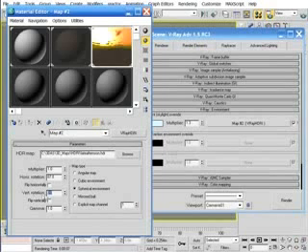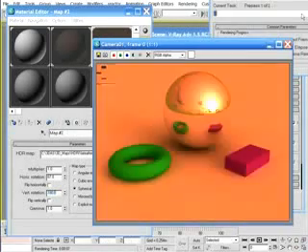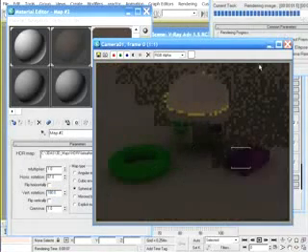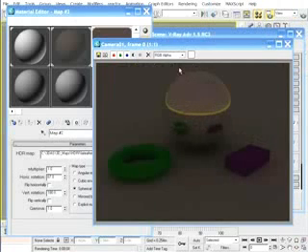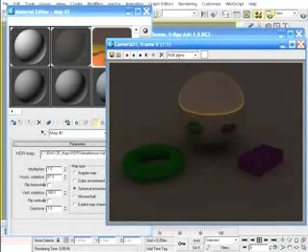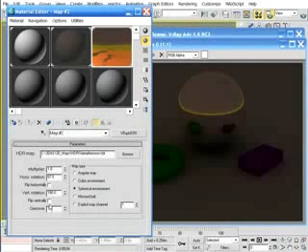And here's the same scene with 180 degrees of vertical rotation. Notice in the sample slot that the HDRI is now upside down. Now when rendered, the majority of the illumination seems to be coming from below, i.e. below the horizon line. You could also just enable the flip vertically option to get the same general effect, although the actual result would be just a mirrored version of this.